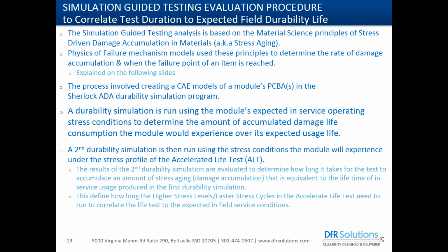And then we can use that to determine how long a higher stress level, faster accelerated life test needs to be run in order to correlate to the same amount of damage accumulation, damage degradation, that would occur in the field life scenario.